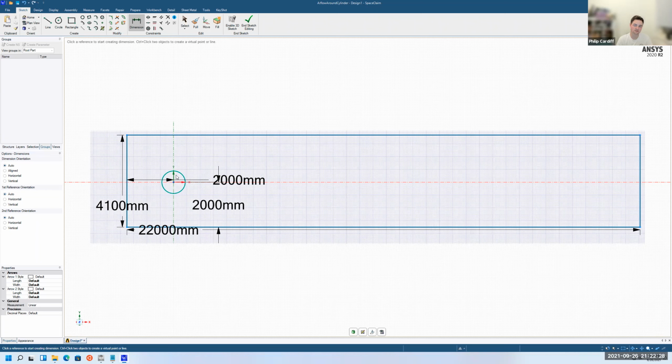So that's on purpose. For low Reynolds numbers, it'll be essentially symmetric flow, but for higher Reynolds numbers, you get vortex shedding. So by creating this slight asymmetry, it'll cause the vortices to shed in a predictable manner.